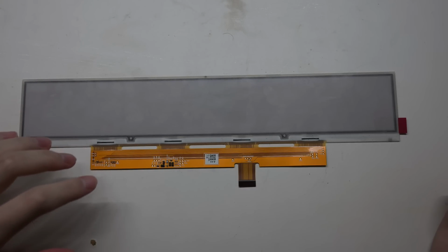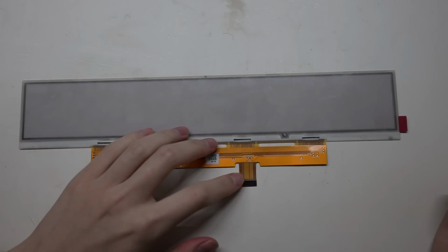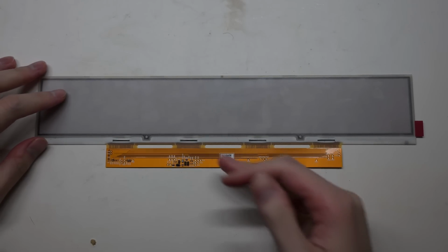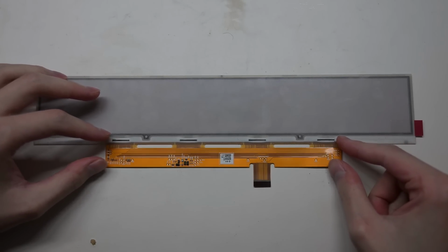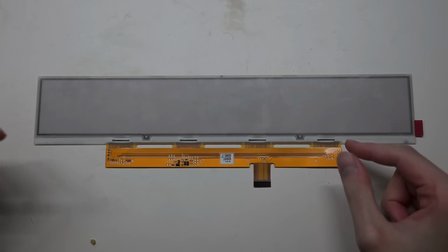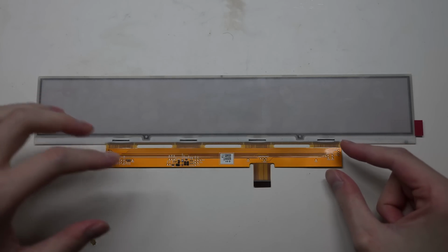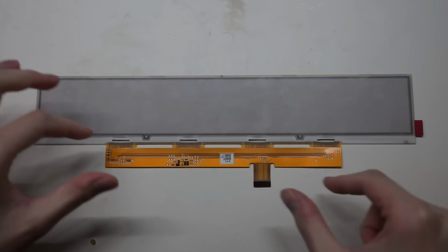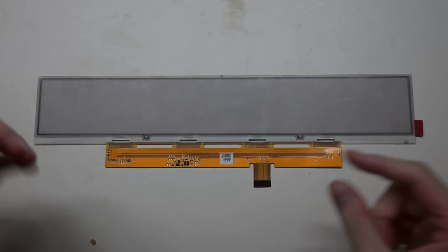Basically, there are two things I need to know. One is the driver IC chip, another is the pinout. So let's start from the pinout. Obviously this is on an FPC cable. One of the good parts about these FPC cables is that the traces are very clearly visible. So if I just take a picture or use a scanner to scan it, I will be able to trace down the lines and know how it's connected. Basically reverse engineer the schematics by just looking at it.